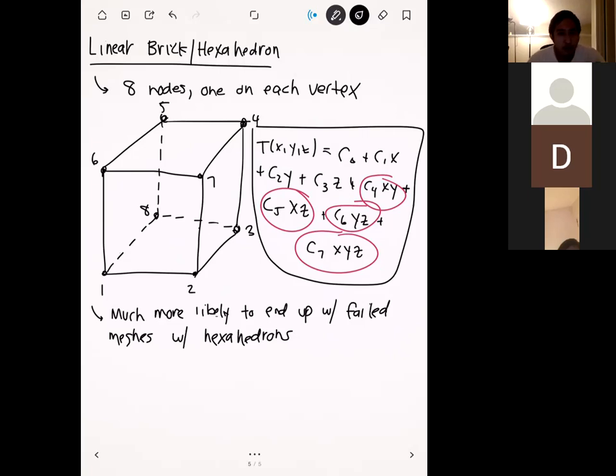And so there are some computers where you might get a meshing error, but another computer might be perfectly fine. That's the annoying thing with finite elements, just because of that random aspect. But it's also good sometimes, because if your meshing isn't working on one computer, you could try it on someone else's computer and see if that works. Then once you get the mesh from that one, you just export that into your model. I'm speaking from experience, and it's happened to me quite a bit throughout my research life, that my mesh would fail on one computer, but it would work on my friend's, so I'd make him do it, and then I'd just get the mesh from him after that.